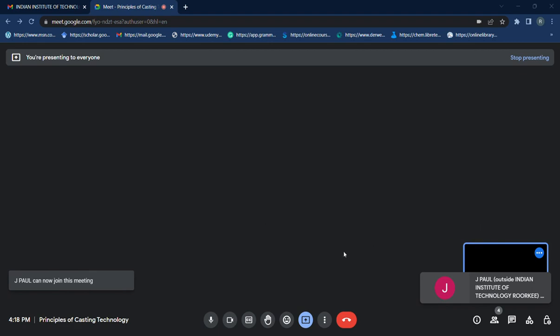Sorry, I think I did something wrong. You have your volume of the riser divided by the volume of the casting as 0.575. So now you can calculate the volume, which will be around 894 cubic centimeters.